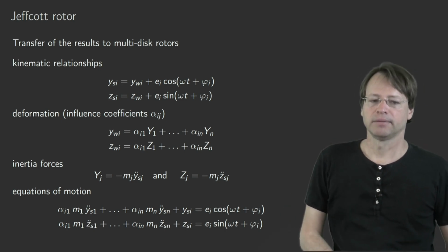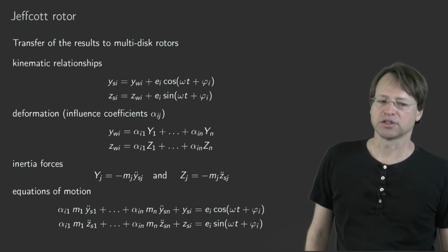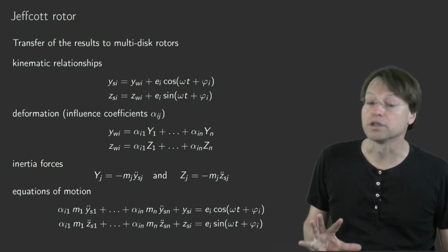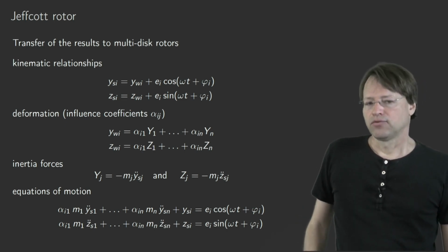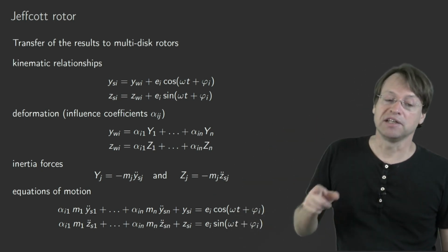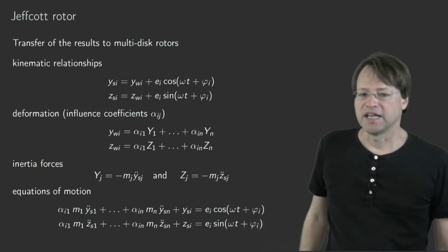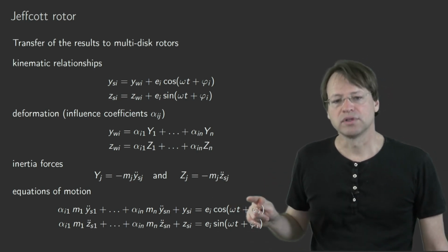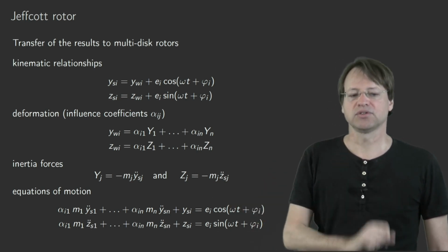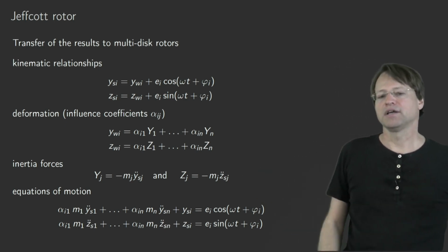Again, for the homogeneous system, we use an exponential setting. This leads to an eigenvalue problem. From the eigenvalue problem, you would find, first of all, the natural frequencies of the system, but with respect to the particular solution, of course, you then see that these natural frequencies correspond to the critical speeds, in the sense of a resonance phenomenon that should be avoided. And guess how many eigenvalues are there?